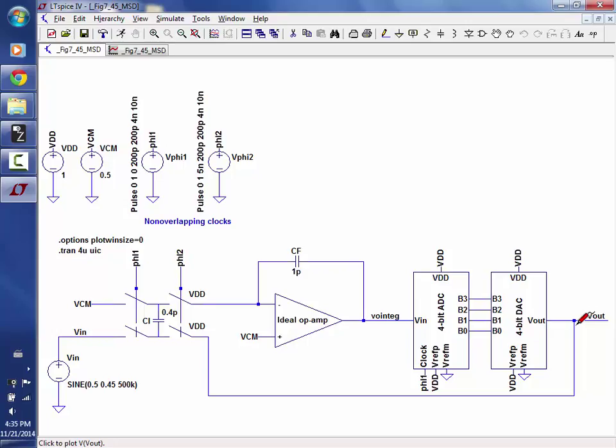mismatch. Let me ask a question. I'm going to ask some really simple questions. If this is used for an A to D converter, where do I take my outputs? Where's the output of the circuit? Yeah, output of the ADC, just like always, right? These are the outputs. Those go to the digital filter. Does everybody follow that? Okay, this is the feedback loop. So if I ask you, which is more important, the performance of the ADC or the DAC, and why?